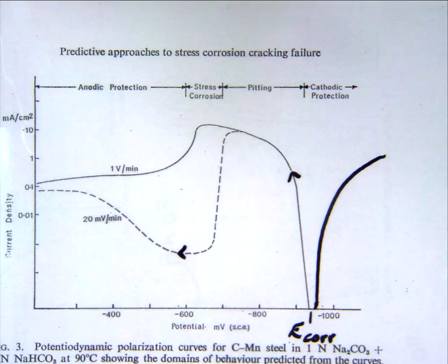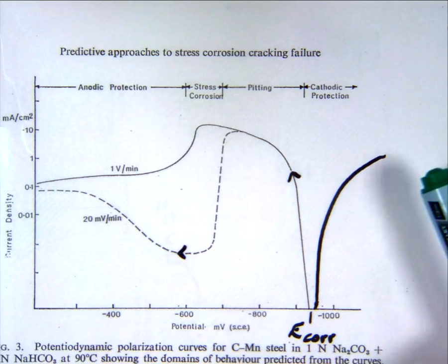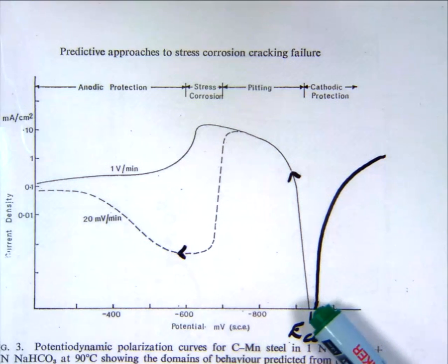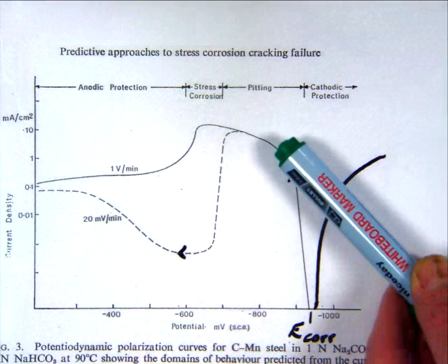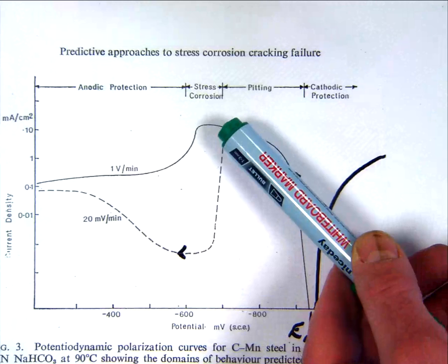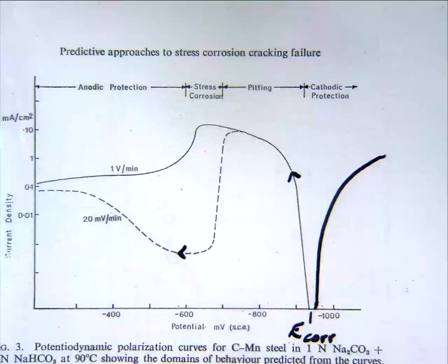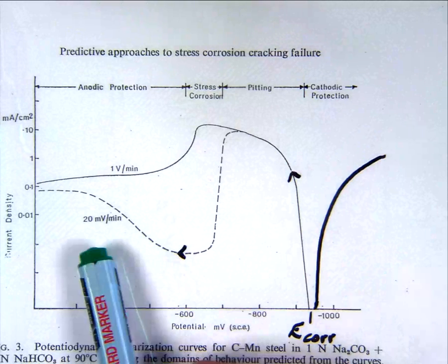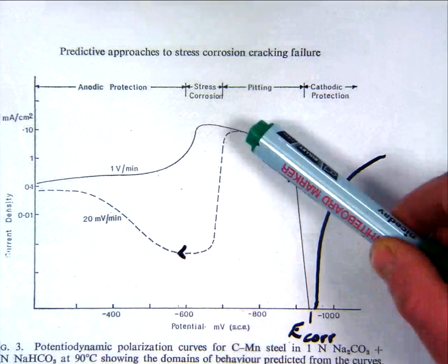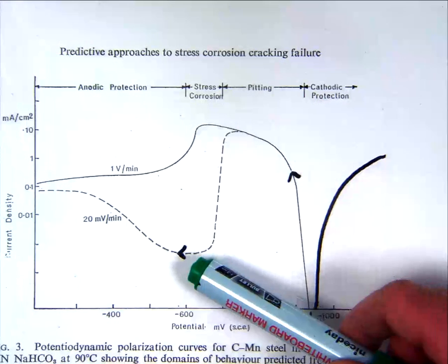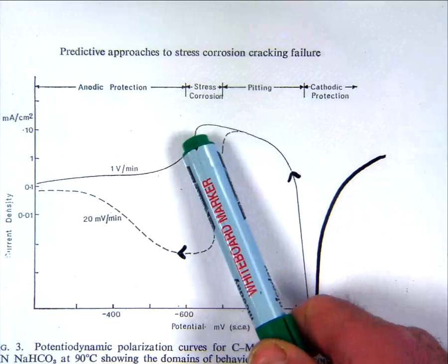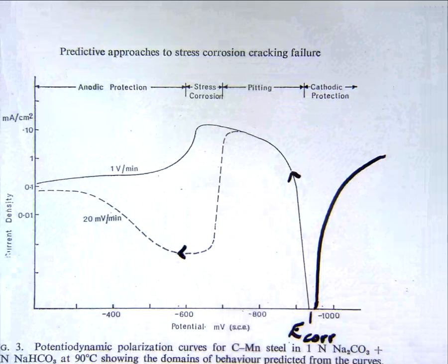And that's essentially the condition that you want for stress corrosion cracking. What you want is, we put a crack in here, or a defect. We want the surface to passivate, and the part of the sidewalls to passivate. But if fresh material is created at the crack tip because of the tensile loading, we want the material underneath to corrode.